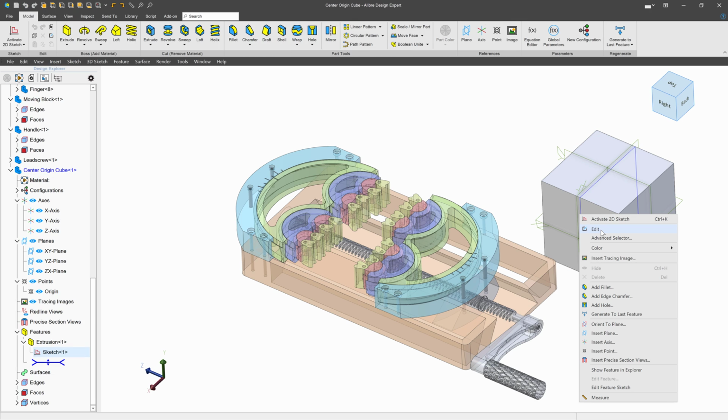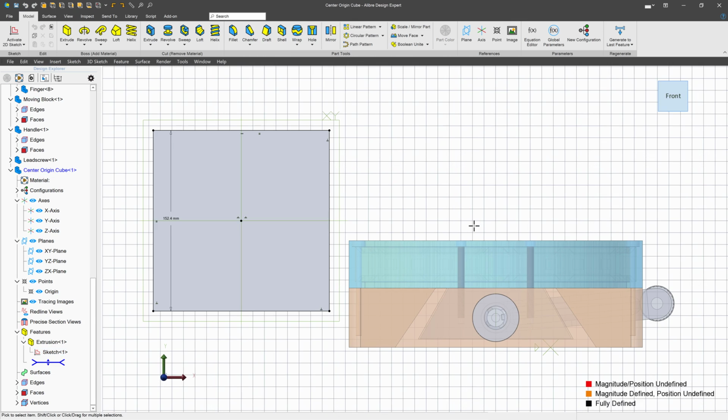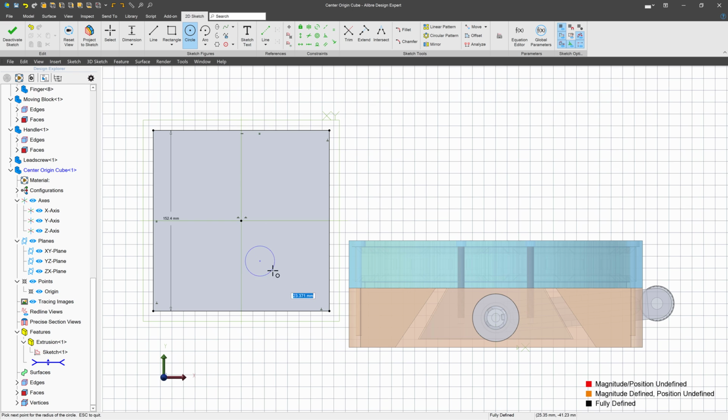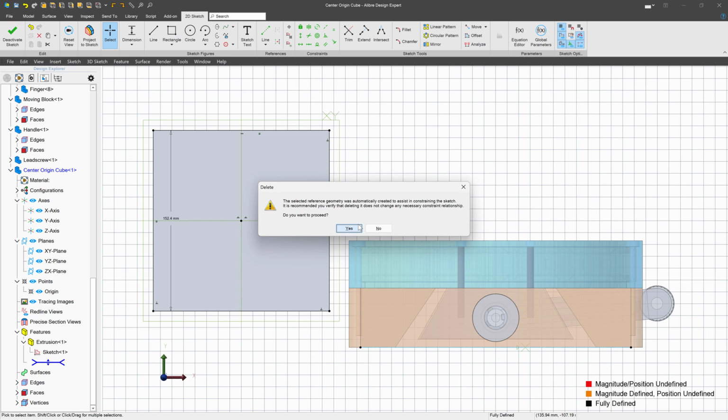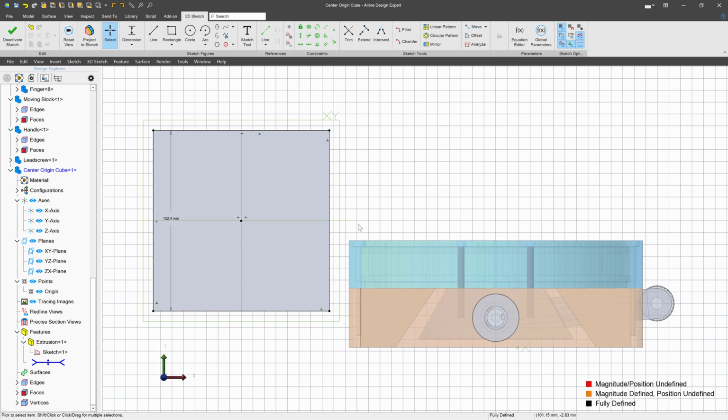And what else is interesting is if I go to edit, say, a sketch, I can actually make this related to parts of my assembly, right? If I want my circle center to be on this bottom axis, I can start making sketches that are integrated into the assembly. This is known as editing in context. I don't want to do that here, but it is important to know that if you need to relate one part to another part, an assembly edit in context is an option.